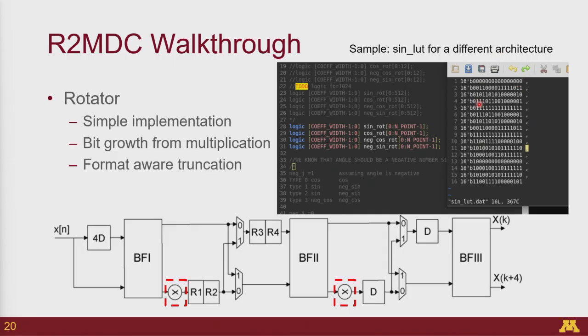But you can't represent 1, it will be 1 minus delta. Yes, so that's exactly the thing here. If you see here, it is like 0 and all ones here. So that is that 1 minus delta. But if you are doing the bypass, when multiplying by 1, you actually don't multiply by this. Bypass. Yes. So that is what I was talking about, those trivial multiplications. If you're multiplying by +1, -j, -1 or plus j, you normally don't actually pass it to the rotator, you just use bypass circuits or interchange circuits to handle those kinds of situations.